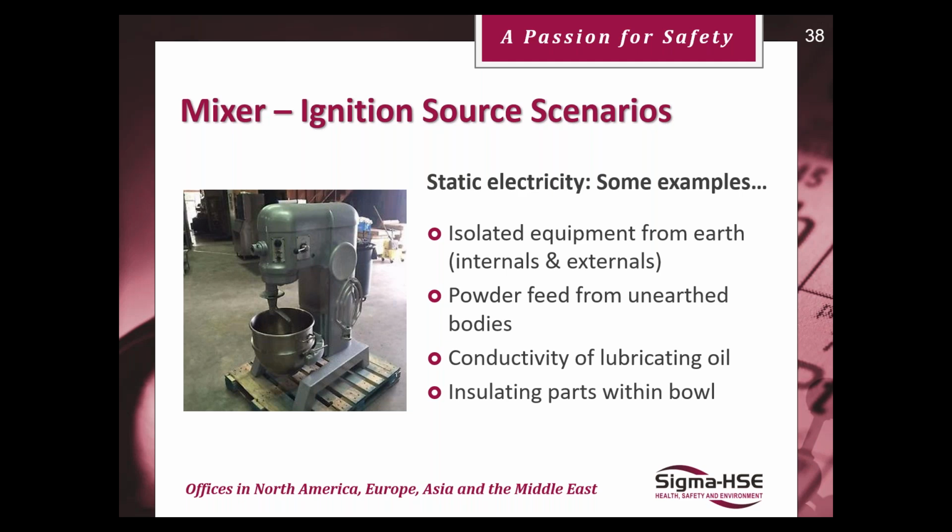Let's see, conductivity of lubricating oil. Maybe the oil might be exposed. Although you can't see it on the mixer unit, maybe it's exposed and the vapors can ingress inside the casing of the actual mixer and contact this, and maybe that can create a spark.